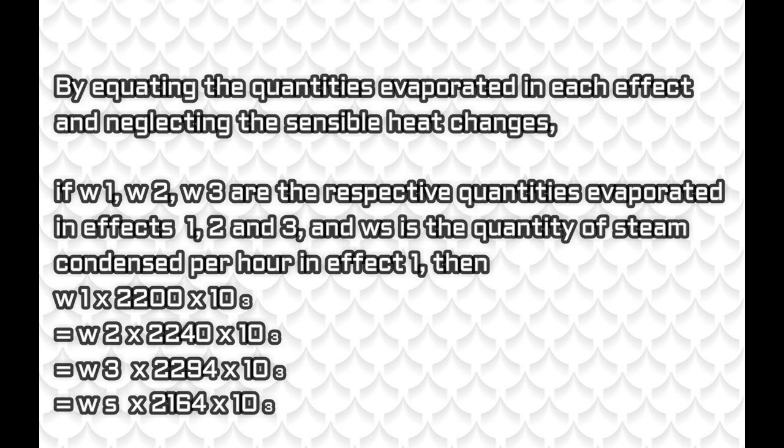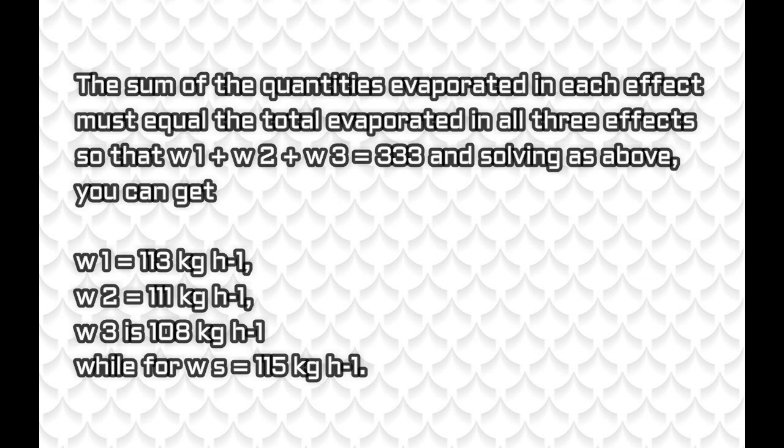The sum of the quantities evaporated in each effect must equal the total evaporated in all three effects, so that W1 plus W2 plus W3 equals 333, and solving as above, you can get W1 equals 113 kg per hour, W2 is 111 kg per hour, W3 is 108 kg per hour, while Ws is equal to 115 kg per hour.